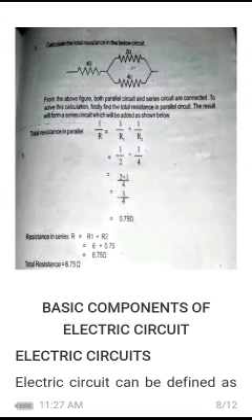The 0.75 ohms will now be in series with the first resistor that you have as 4 ohms. So now they are in series to each other, so you can say resistance in series. You state the formula again, which is R equals R1 plus R2. And what do you have for R1? You have 4 ohms. And for R2, the one that you just finished now is 0.75.